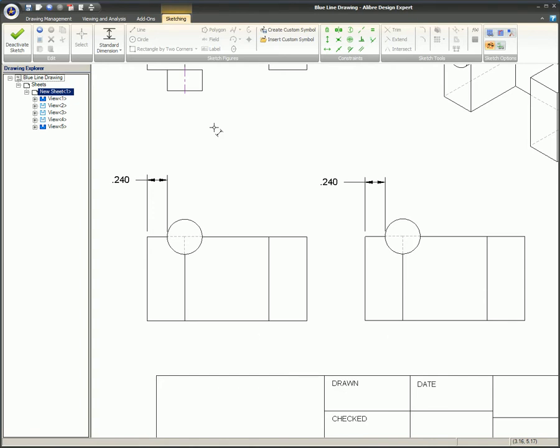the edge. Blue dimensions will appear under a set of specific circumstances, particularly when a part is initially dimensioned in a precise view and then reprojected as a fast view, where that dimension refers to a line or edge that has been broken by another feature or part.